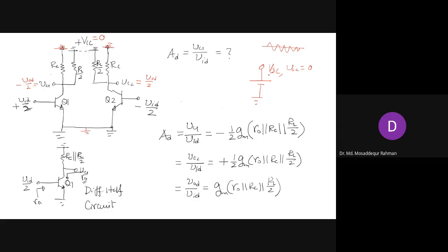And you have some DC voltage here, some amount of it can be 5 volt, can be 10 volt, it can be low, it can be high. But as long as the small signal voltage is constant, there is no fluctuation. So that is 0. And an ideal source has 0 resistance, right?